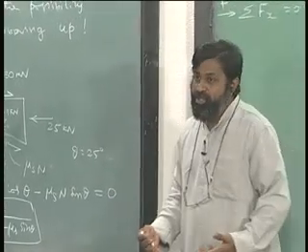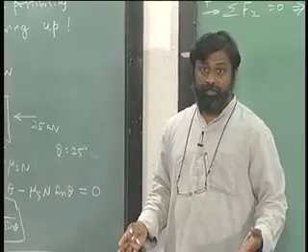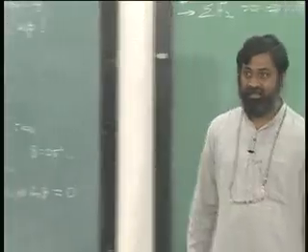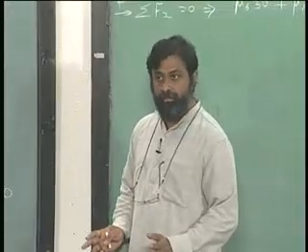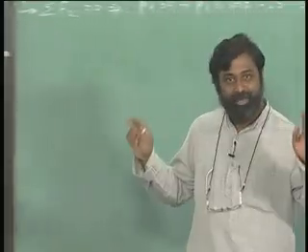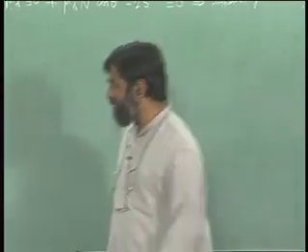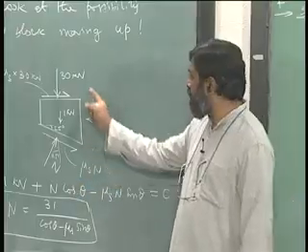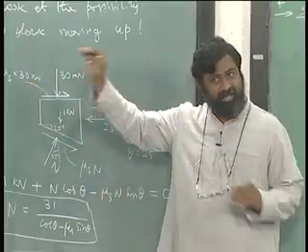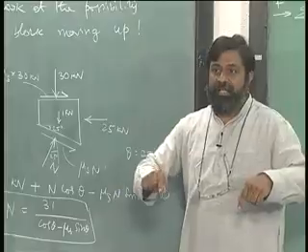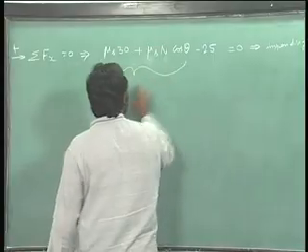If it is in motion, let us say there is an acceleration, remember it is not equal to 0, it will have mass times that acceleration. If it is not moving, if it is not impending, these assumptions that I have made are not correct. So, remember so many assumptions that I have made. But what is true here is this value mu s times n or mu s times 30 are the highest values that are possible if it is in static condition, and therefore, if the values are lesser, we will find out what is happening. So, let us look at this, these two are the frictional resistance.